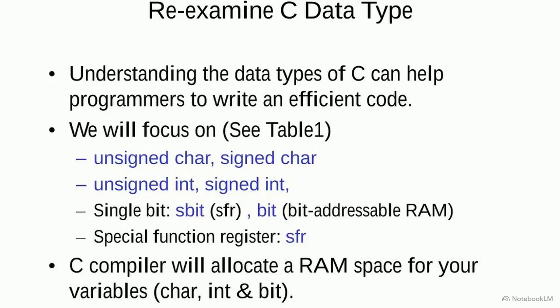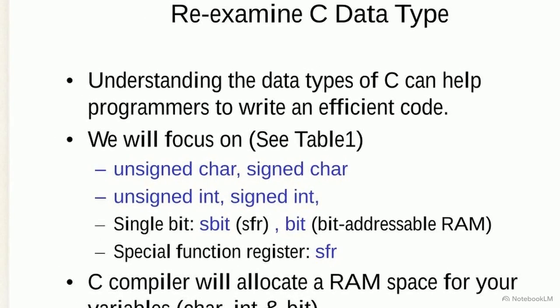This table outlines the specialized data types provided by 8051 embedded C to solve this constraint. The unsigned char must become the default replacement for standard integers. It occupies one 8-bit byte and holds values from 0 to 255,